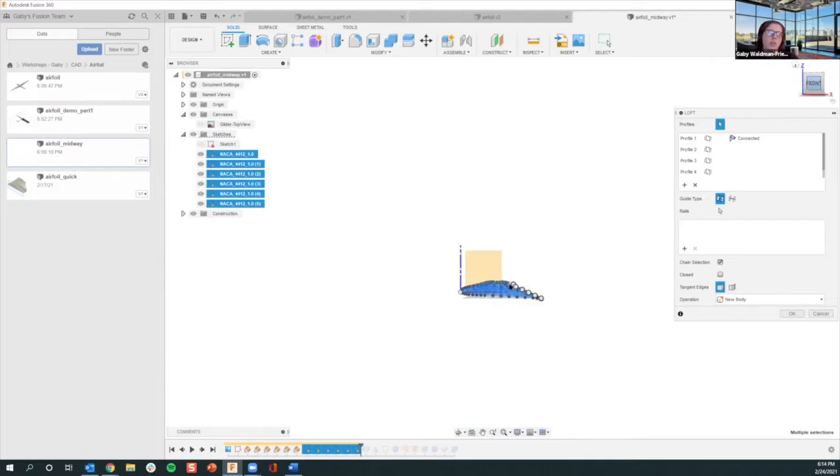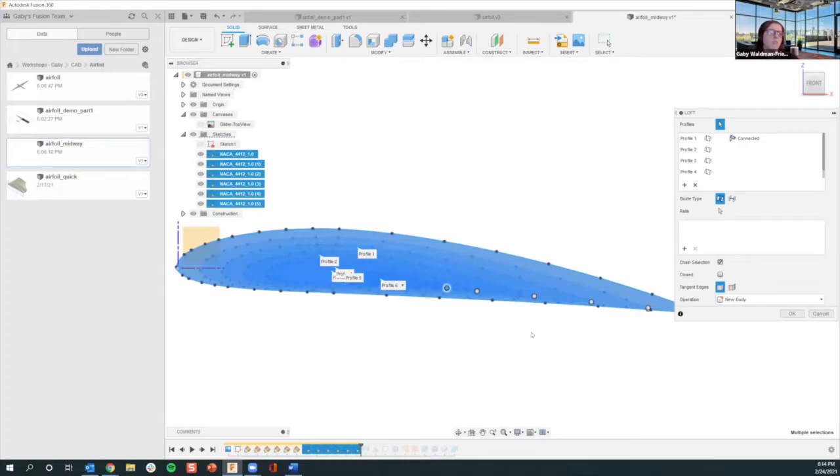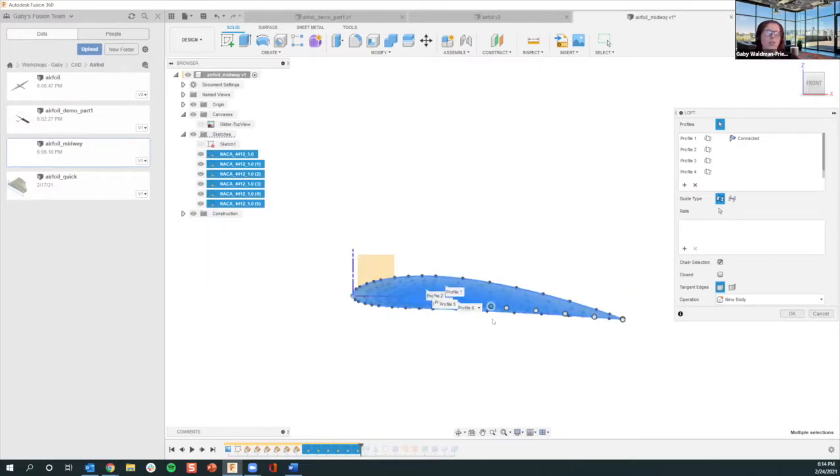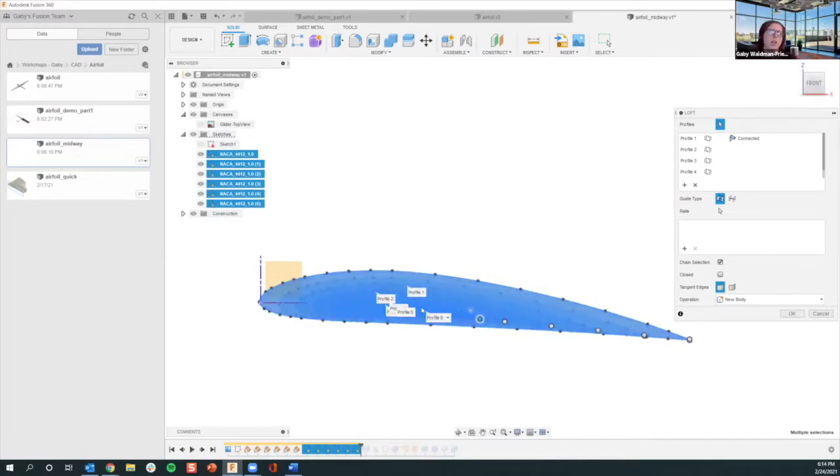One thing you'll notice here is that I was able to rotate the foil. So when I put in this DAT file with the profiles, I was able to rotate them slightly. The first one is rotated up, the angle of attack is high. What that means is that, if this is horizontal, the angle of attack is something like that. It's an alpha symbol, I believe. And we want it to be high or higher, and then we're rotating it down. I believe that's how I did it. Now it's been a couple weeks, but actually, let me scratch that. It might have been that I put a negative angle of attack and then I slightly rotated as it went down the wing to be a positive angle.